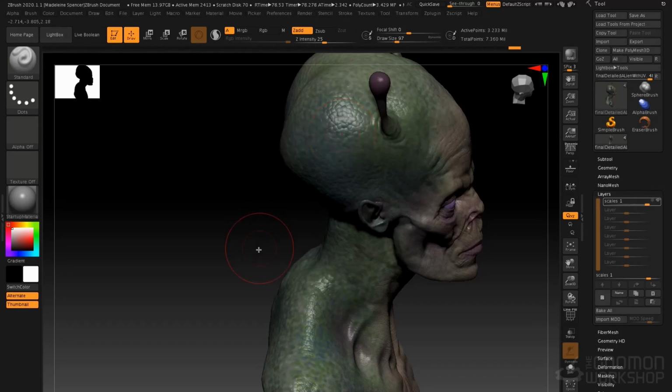That's another important thing to keep in mind with layers. Once you create a layer, you have to be in a recording layer to change your model. So now I can adjust the intensity. If I turn this down, you see it changes the opacity of that layer. I can even go into the negative range and invert that so it's pressing in instead of out. We'll bring that back up to 100%.